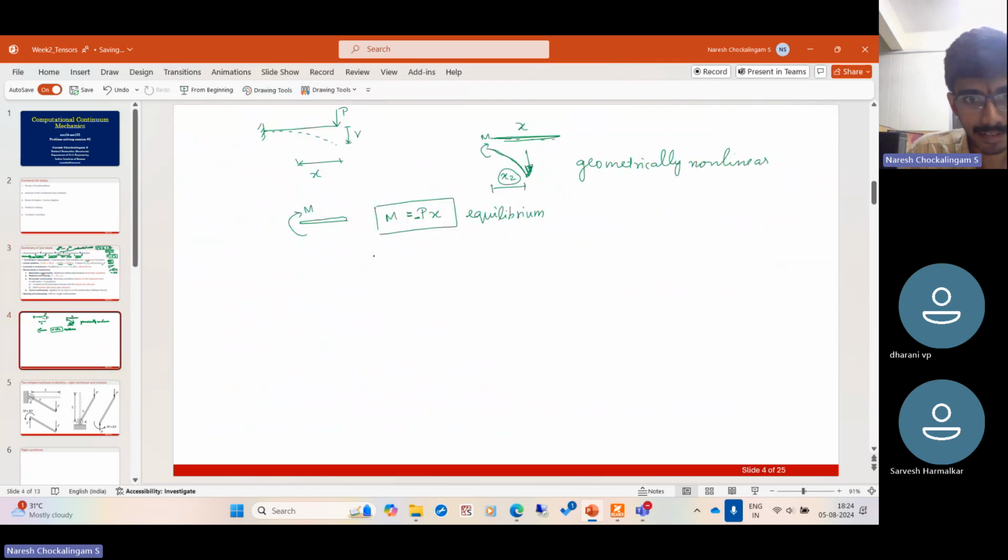The second thing is, in a given section, from beam theory, the stresses are linearly distributed. So actually the strains are linearly distributed, and the stress and the strains are related as sigma is equal to E times epsilon. However, say when you have plasticity, if it is yielding, the stress cannot increase beyond the yield stress.